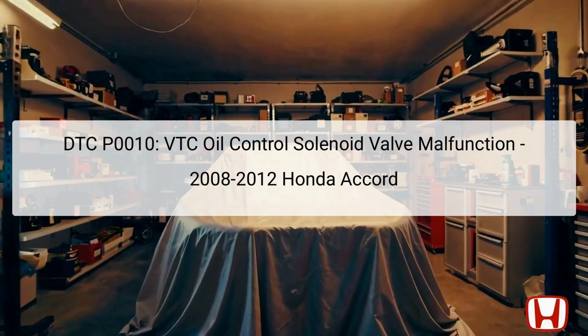The Diagnostic Trouble Code DTC P0010 refers to a malfunction in the variable timing control VTC oil control solenoid valve, a critical component in engine management. This solenoid plays a vital role in regulating the flow of oil to the VTC assembly, which adjusts the camshaft timing for optimal engine performance and efficiency. The VTC system enables variable valve timing, helping improve power, fuel economy, and emissions.